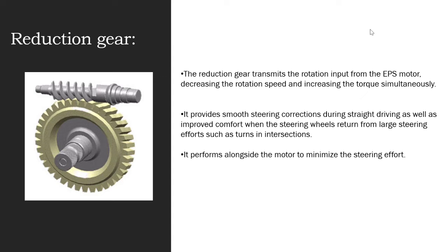Let's see what the reduction gear is. The reduction gear transmits the rotation of input from the EPS motor, decreasing the rotation speed and thus increasing the torque simultaneously. So when the driver applies the steering for a slight turn, it provides smooth steering corrections during straight driving as well as improved comfort when the steering wheel returns from large steering efforts such as turns at intersections. So it also works alongside the motor to minimize the steering effort.